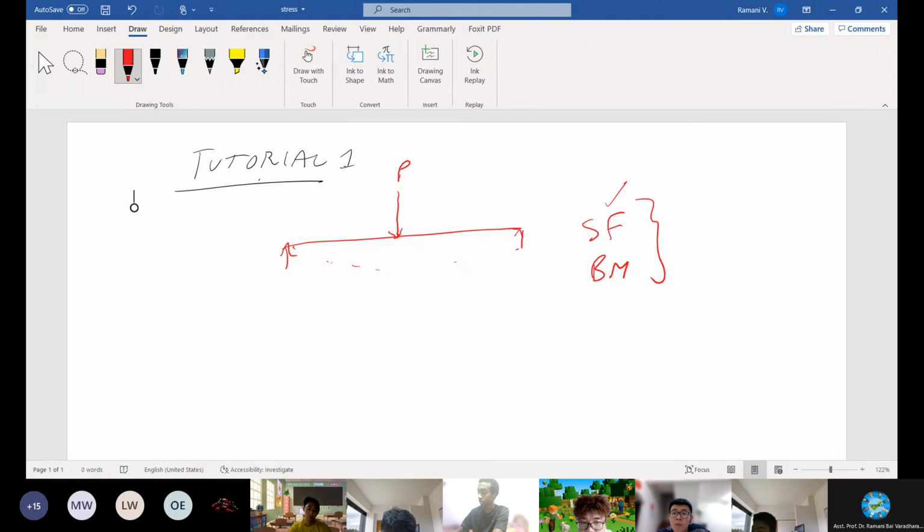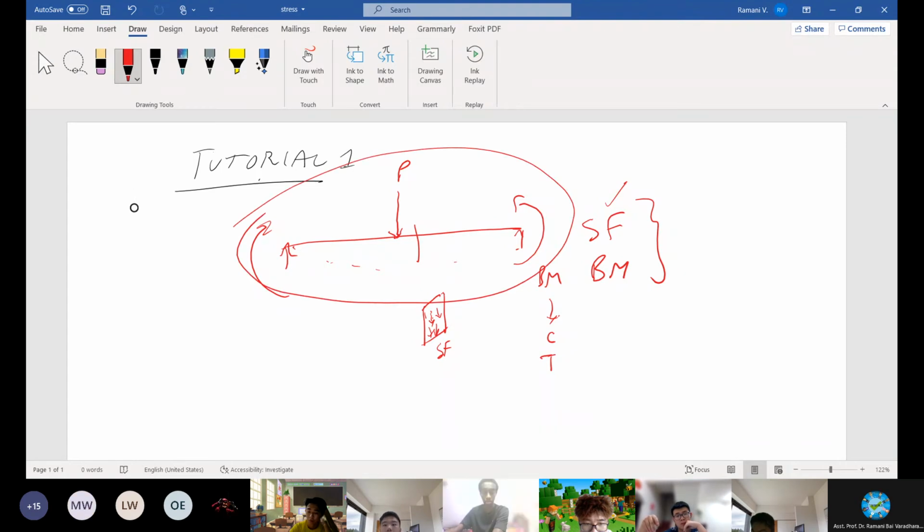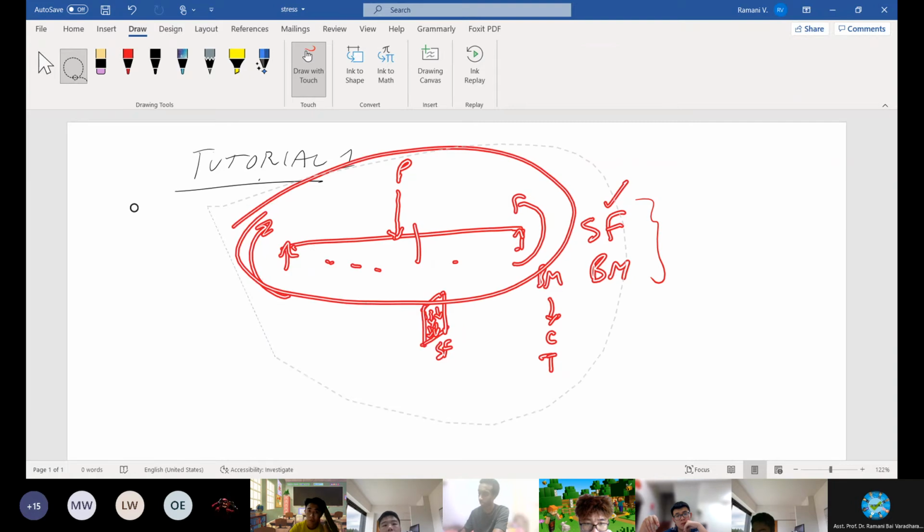When you take the shear force, if you cut the cross section, maybe a rectangle, the shear force will be acting across the cross section like this. On the other hand, the bending moment will tend to bend, in the clockwise or anti-clockwise direction. So you found out what shear force is acting and what bending moment is acting. Later you will study whether the bending is compression or tension. But this part you already studied in your engineering dynamics, correct? Now coming to